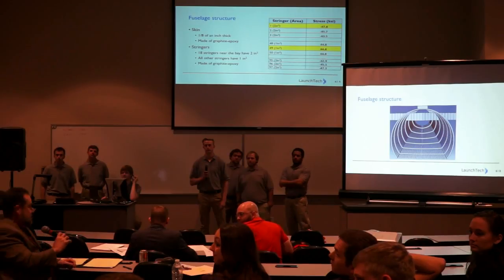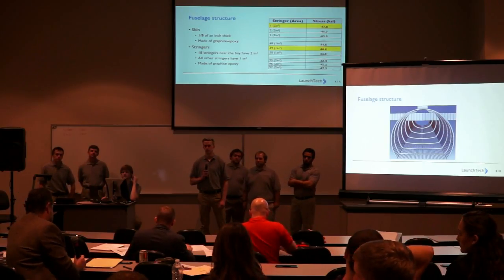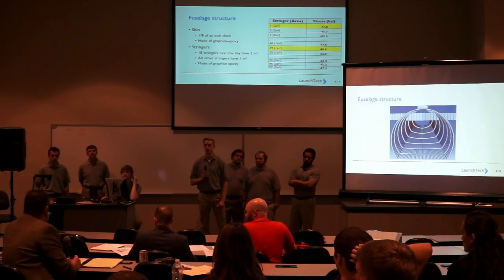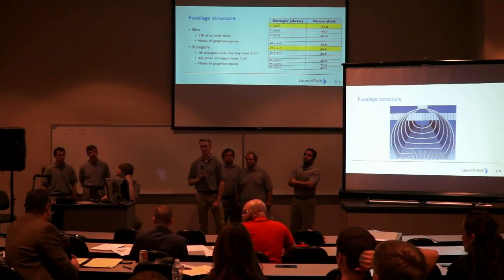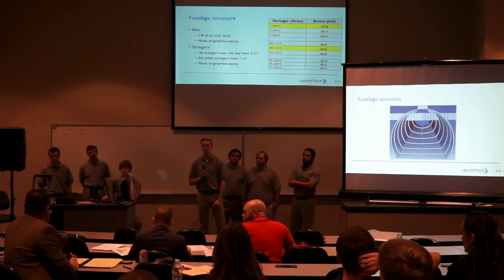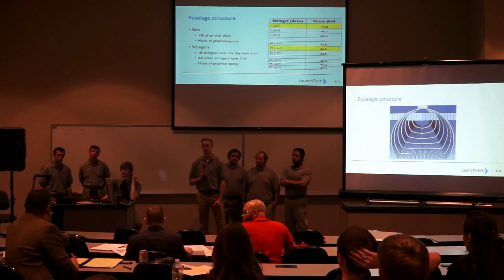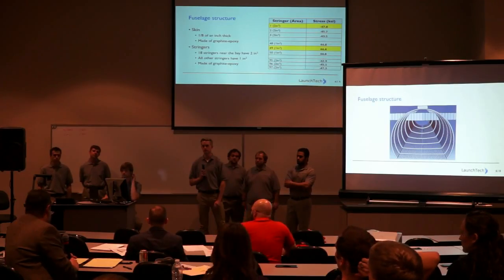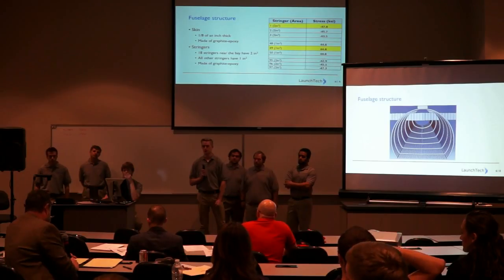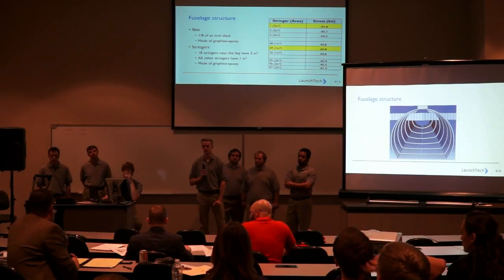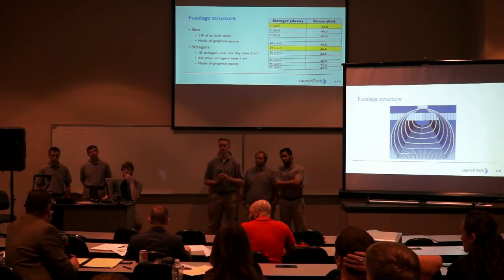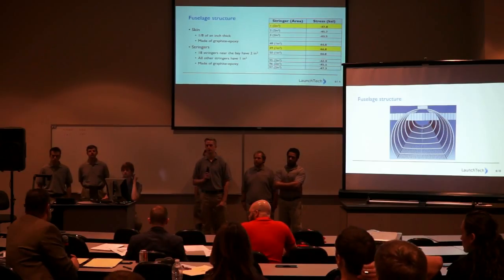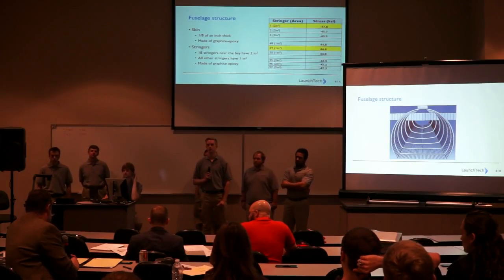Mr. Haslam has another question? I didn't have a copy of the slides, so I'm just going to go through in the order that I took notes. I'm worried about the horizontal tail being level with the wing. You're going to get some buffet from that. You may have to move that tail, probably off of the vertical. The B-52 takeoff approach is a perfectly reasonable thing to do. You are right to be worried about the wing incidence angle and flap setting.